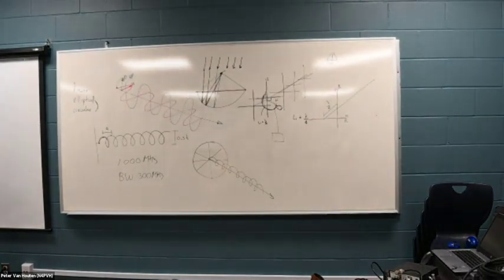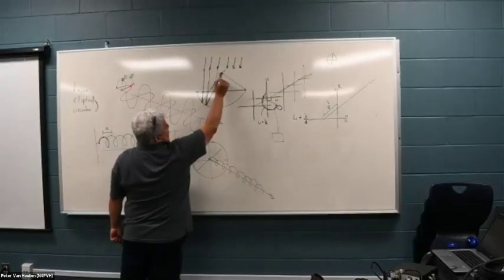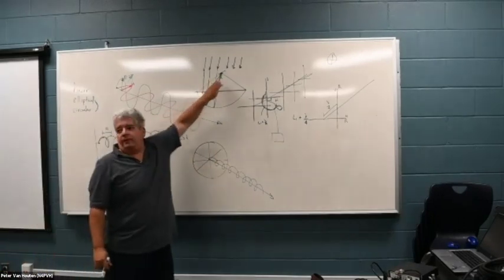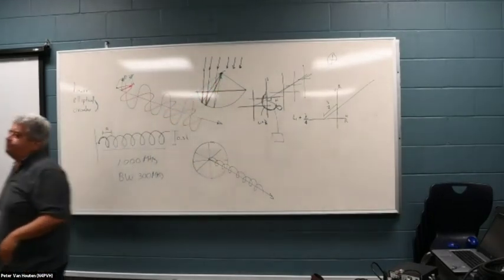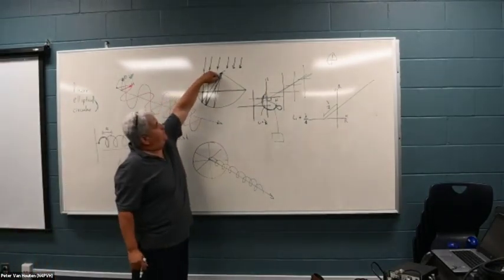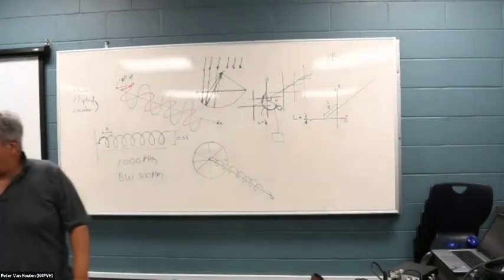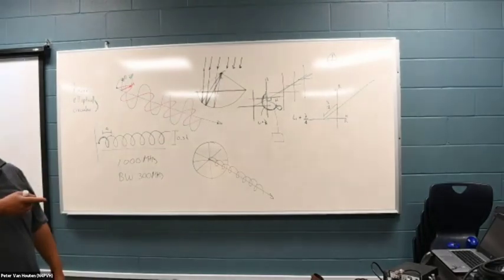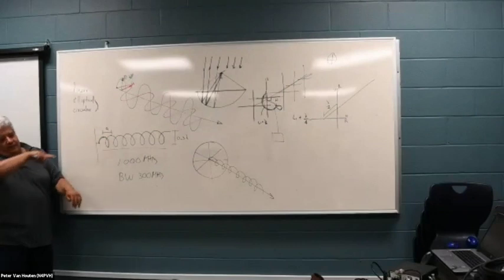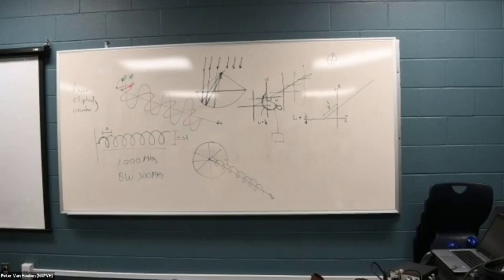Okay. Then you can put a short helix here. There are some dimensions or requirements that you need for whichever antenna you use at this point. And one thing happens. If I build this helix like this, pointing to the dish, meaning right-hand circular polarization, looking from the back of the antenna, from here, I look there, and then I see it this way, clockwise. Okay, that is right-hand circular polarization.